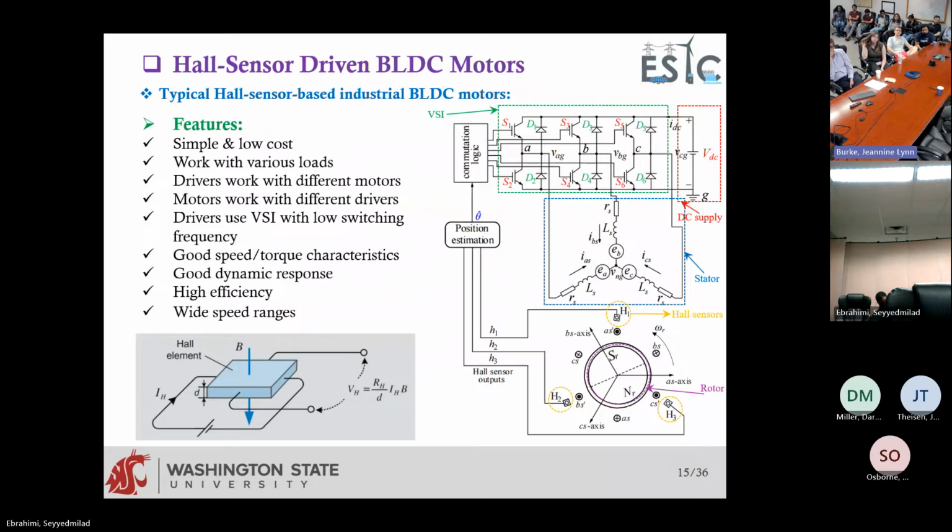Basically, this is the model. So you have a back EMF here, some voltages that I showed you. It can be pure sinusoidal, trapezoidal, quasi-trapezoidal. Inductance, resistance, and whatever voltage is connected determines what the current would be, right? So what would be the sources of the current? You have one voltage source connected here, one here for the three phases. You have RL, and you have another voltage source. So do the math: two voltage sources divided by R and L. It's going to be this one minus this one, divided by the impedance, right?